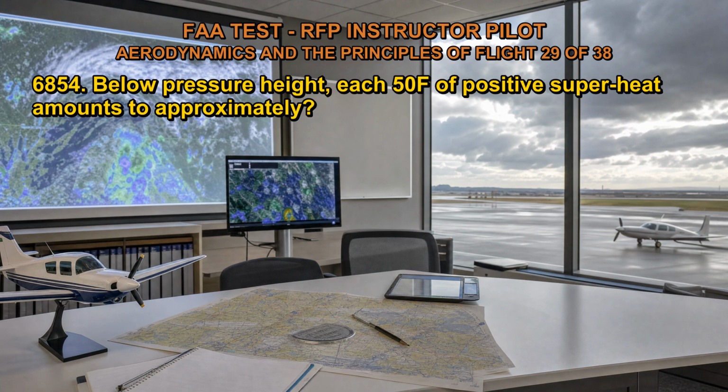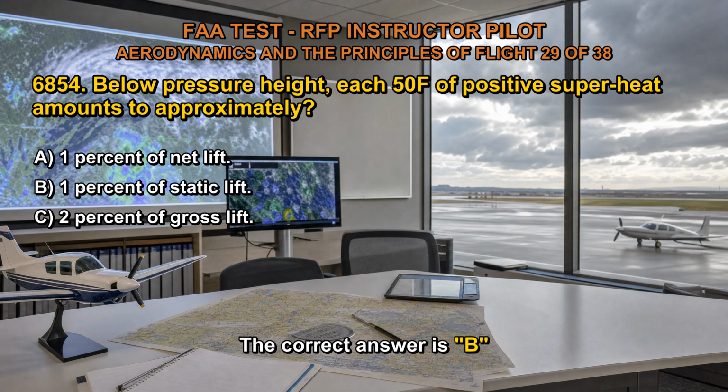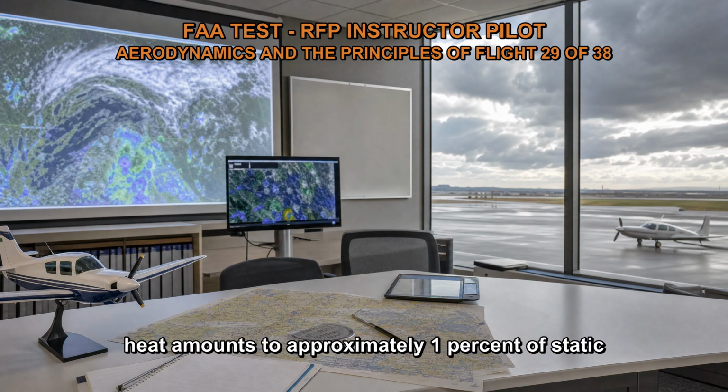6854. Below pressure height, each 50 degrees Fahrenheit of positive superheat amounts to approximately A. 1% of net lift. B. 1% of static lift. C. 2% of gross lift. The correct answer is B. Below pressure height, each 50 degrees Fahrenheit of positive superheat amounts to approximately 1% of static lift.